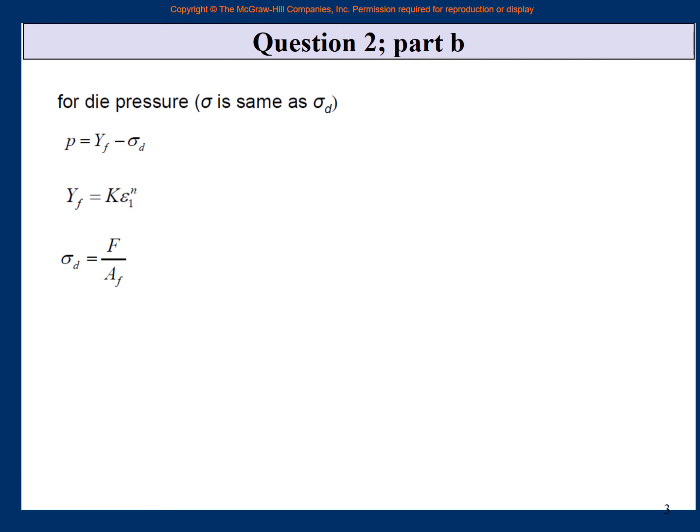So you have found what the force was. Now remember, the force that you initially found was the ideal force. So multiplying by 1.4 will be critical, because this is the actual operation, not only the ideal part. That ideal part is only for doing calculation and so on. But the real one is ideal plus friction plus redundant total.